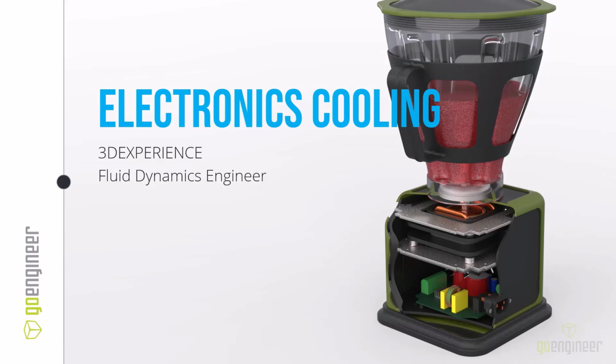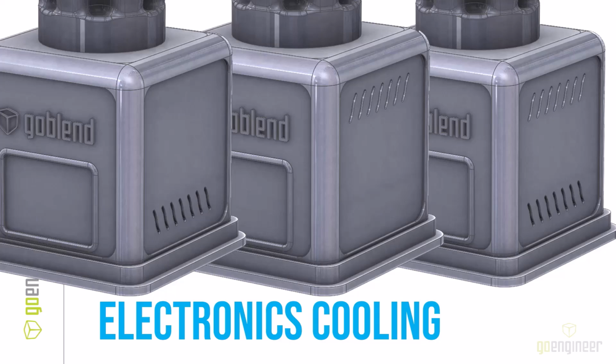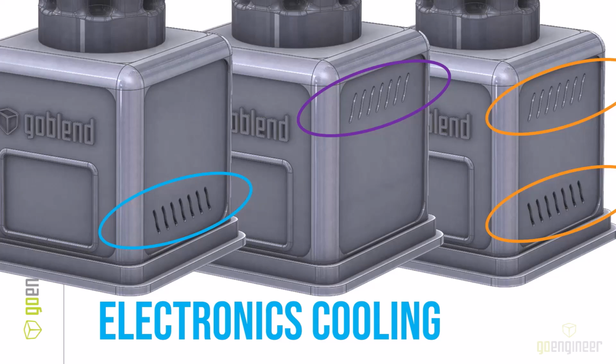So what we're looking at doing is adding vents to the sides of the blender to kind of understand, is the controller board going to exceed the chip's maximum temperature? That maximum temperature is 85 degrees C, and we need to make sure that we stay within that. Now, we're going to be doing an electronics cooling analysis using CFD, computational fluid dynamics, and we really have three areas that we can add vents. So on both sides, we can add vents to the lower section. We can add vents to the upper section of the blender on both sides. This is actually what marketing likes the most. And as an engineer, I kind of feel that we need both the top and the bottom, and we're going to try to prove that out.